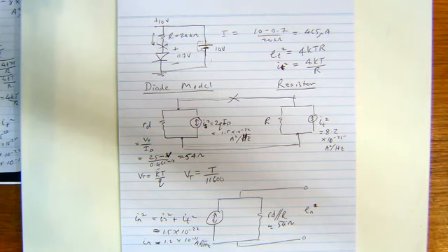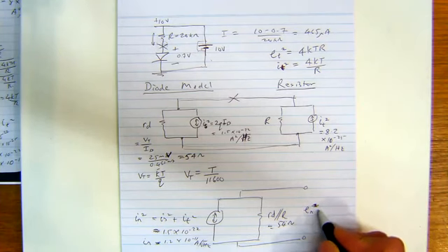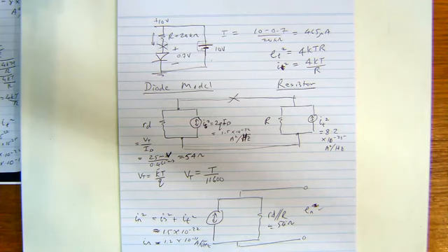So it's, I don't know, 70 times 10 to the whatever. Alright, well, that'll give us an EN value. And that's a spot noise again, yeah? It's one spot in the frequency range, which is going to be constant, because the processes are white. Both the shot noise and the thermal noise are white in spectrum.